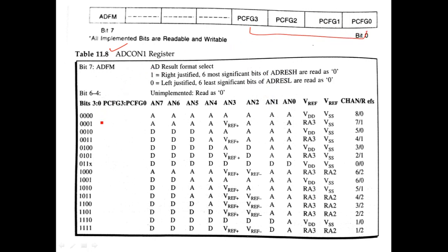These 4 bits have 16 combinations, and they decide the function of various input pins that are used by the ADC section. If you remember, the ADC analog input channels are provided on different port pins. So different port pins have alternate functions of carrying the analog channels.